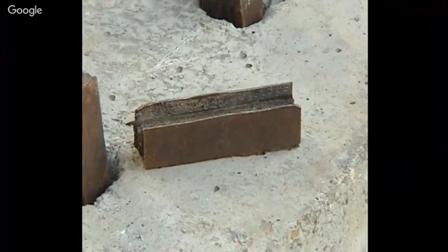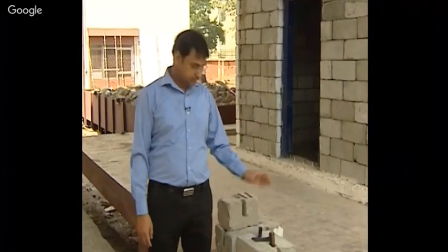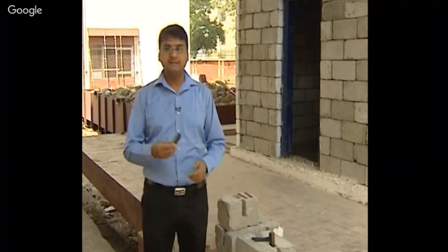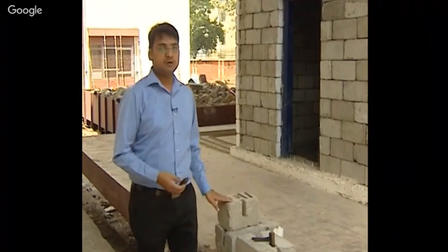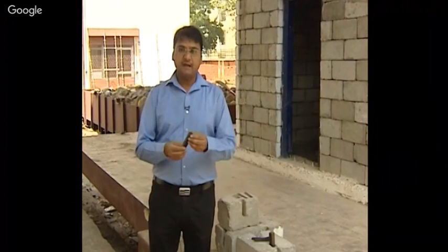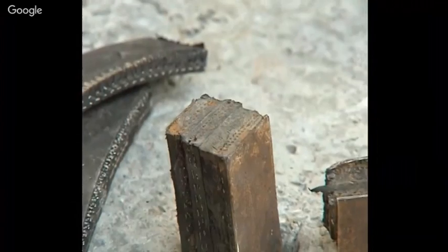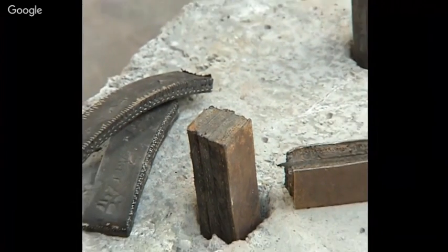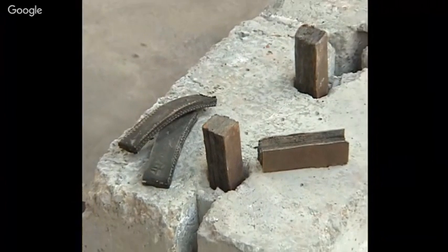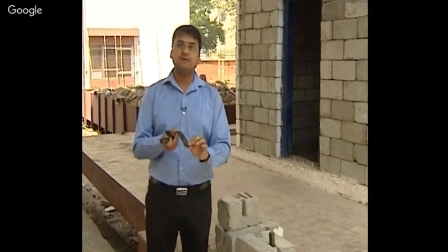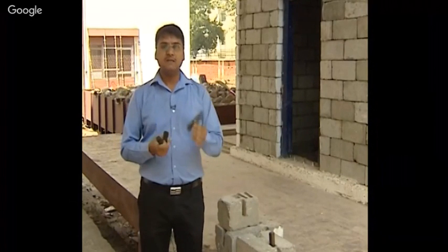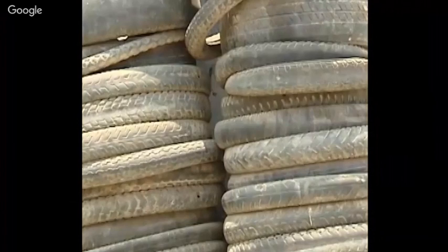The interlinked block masonry system with viscoelastic link is a technology in which two parts are there. One is the viscoelastic energy dissipator link, and the second is the interlinking block. This interlinking block is joined using the viscoelastic link, which is developed using used and old rubber tires. And why have we used these old and used rubber tires? We have used the ply of the used rubber tire. The ply has steel wires embedded diagonally into it and has the property of viscoelasticity, while the steel wires provide strength to the material. So we have used both properties of the material and converted this waste material into a useful material.